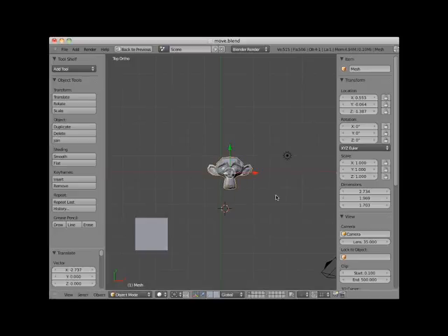Notice that I can also select the monkey object, press the G key followed by the X key, and move the object one Blender unit at a time by clicking on the up-down arrow buttons on my keyboard. I will left-click to stop the translation.